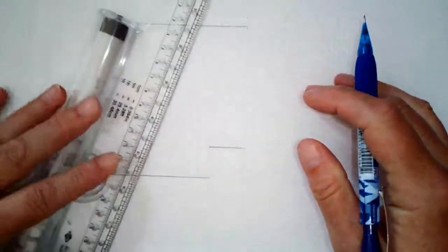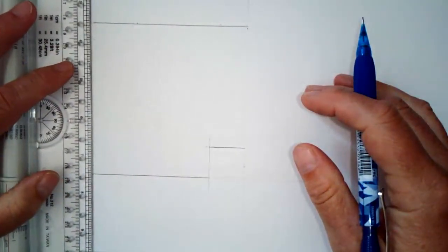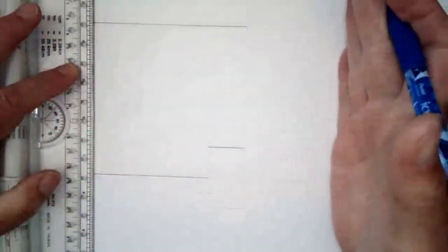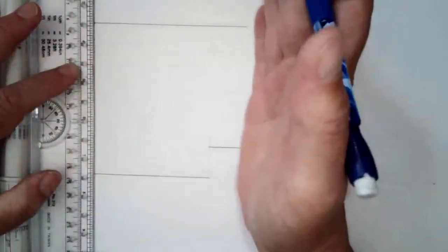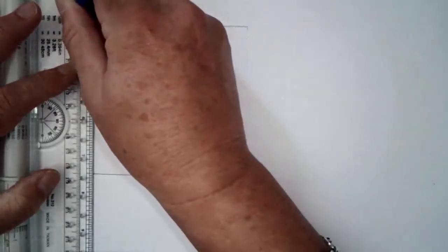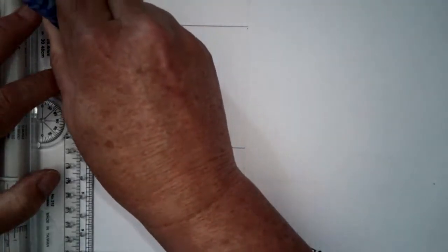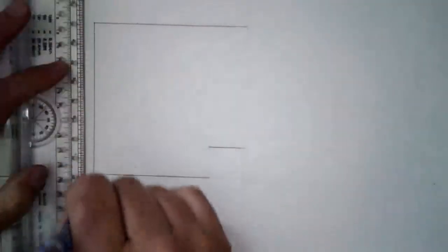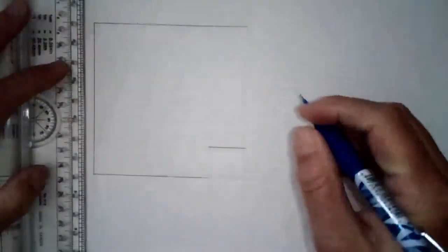I'm going to switch my straight edge to a vertical position, and starting from left to right, because again you're going to smudge less. If you're going this way, you're going to start smudging the lines you've drawn over there on that side. This is especially important when you're inking and you need some time for the ink to dry. And I pulled the pencil towards me again, not pushing it away from me.